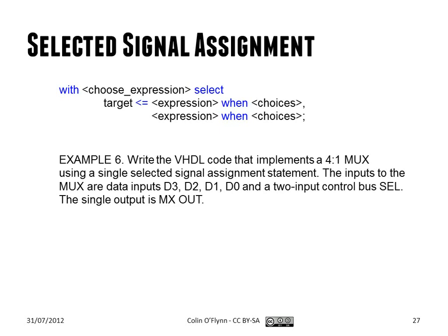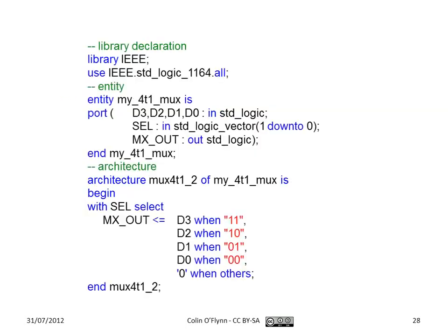We can also use a case statement, which, similar to the last one, we're using it to, based on some inputs, decide what to do. It tends to be a little cleaner. So we're saying if we want to have a mux, a 4-to-1 mux again, and now what we're going to do, these are just single bits.